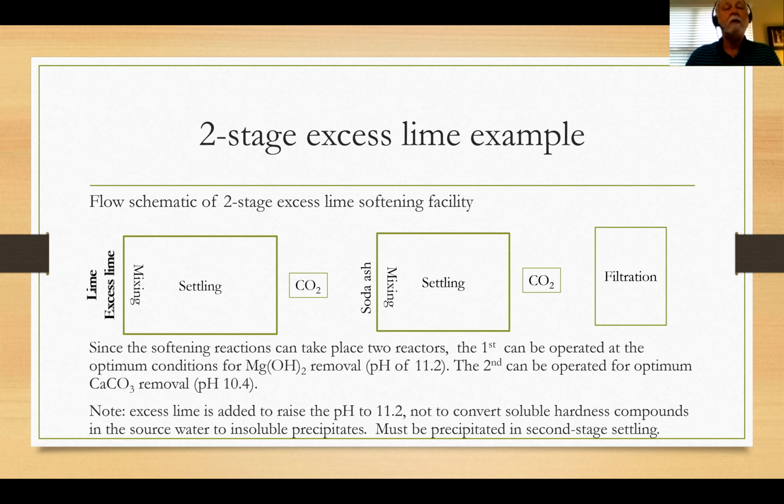There have been reported cases of people scratching their heads because they're flunking lead and copper, particularly lead, but their water seems fine. They've got 50 milligrams per liter of alkalinity as calcium carbonate at least. They've checked their buffering capacity is good. But they still have problems with lead, and sometimes it's Larson's ratio that we don't always look at, or it's calcium to magnesium ratio. And with split treatment, I can actually control the calcium magnesium ratio. Okay. So that's kind of the other examples.